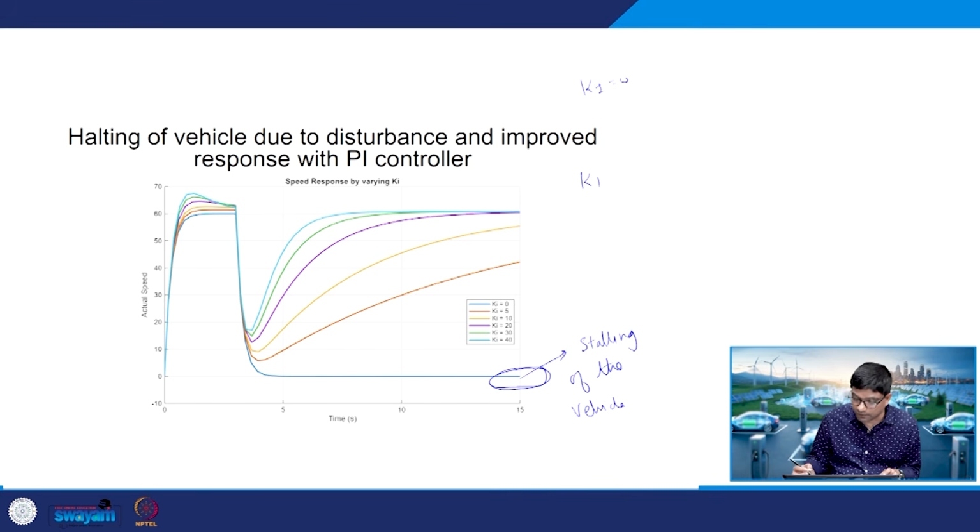So what I do now is I put a small Ki at 5, and you see the speed is actually coming closer to 0. It kind of slows down, but eventually picks up, right? You can maybe see this in a car which has a cruise mode.